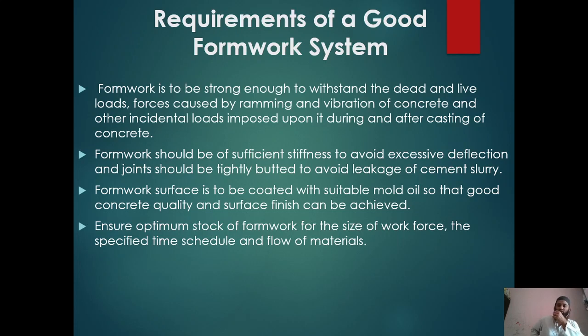Formwork surface is to be coated with suitable mold oil so that good concrete quality and surface finish can be achieved. So it should be coated with oil. Basically, we use oil, which is coated on the formwork, because a smooth finish is also required here. To ensure optimum stock of formwork for the size of the workforce, the specified time, schedule, and flow of materials is also important. If the formwork is very good, within time we can speed up the construction, and we can achieve desired results also.